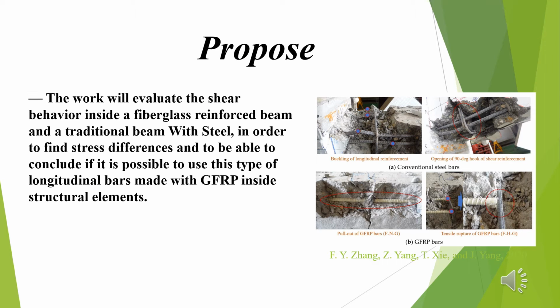The purpose of this work is to evaluate the shear behavior of fiberglass reinforced beams and traditional beams with steel, in order to define the stress difference and to conclude if it is possible to use this type of longitudinal bars made with GFRP inside structural elements.